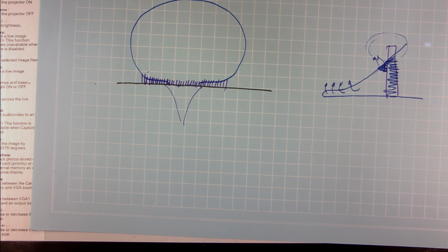So, the more wicking the surface is, the more liquid I can get into the nanofins, and therefore, more vapor I can produce. So, there is one theory out there that says it is the wickability, how wicking those structures are, that determines how much CHF you can get out of them. But there was one experiment that has discredited the wickability theory. That experiment showed that you had hydrophobic nanostructures, which are not supposed to wick liquid, but it was giving CHF enhancement. So, then how is the wickability theory true?